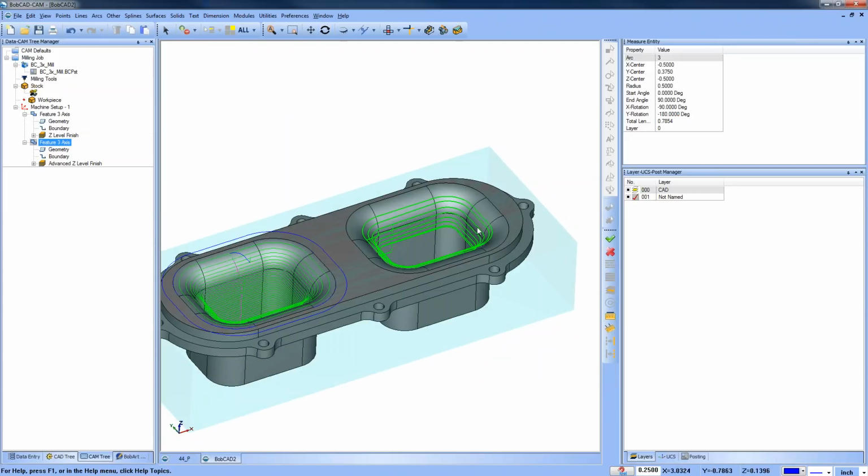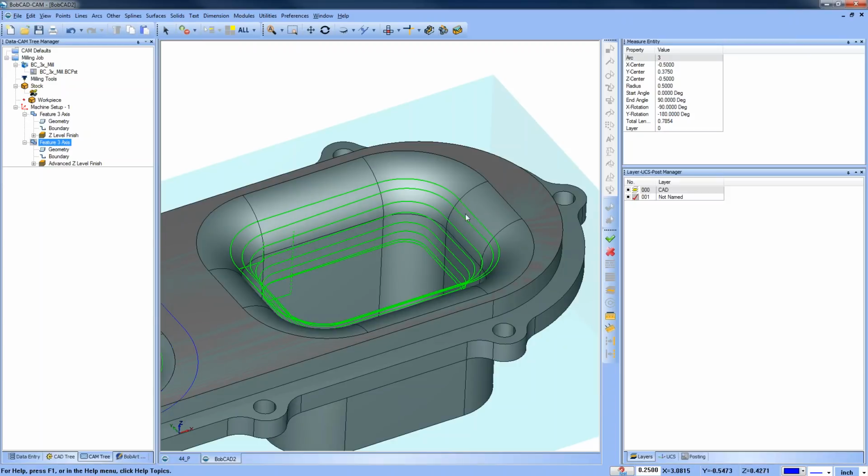Now, Ron had a question, why is it not cutting the full radius? This has to do with the characteristics of this toolpath. This toolpath is best for more vertical geometry versus shallow geometry. And as the radius comes over this edge here, this definitely shallows out. Okay, so what are some of the ways that you can handle that?